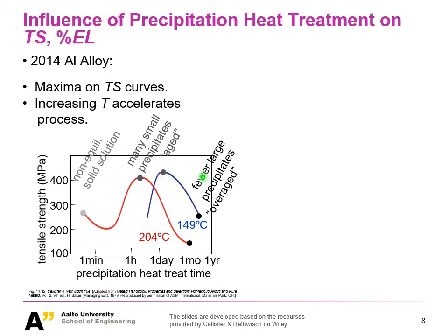Your small precipitates will continue to diffuse, and they will finally grow into somewhat larger theta phase, larger precipitates. And as you can imagine, the boundaries become fewer again, and your material becomes softer. So this is a specific phenomenon related to precipitation hardening.